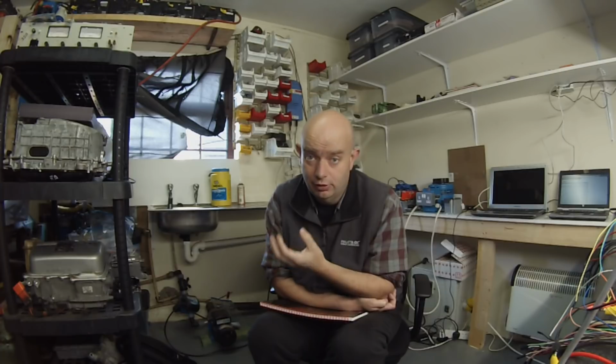And my initial feeling was that what was happening was that the cycle by cycle current limiter, which works in software obviously, was either not working above 700 to 800 amps, or was not quick enough to catch some mysterious current transient that was being caught by the hardware overcurrent detection circuit.